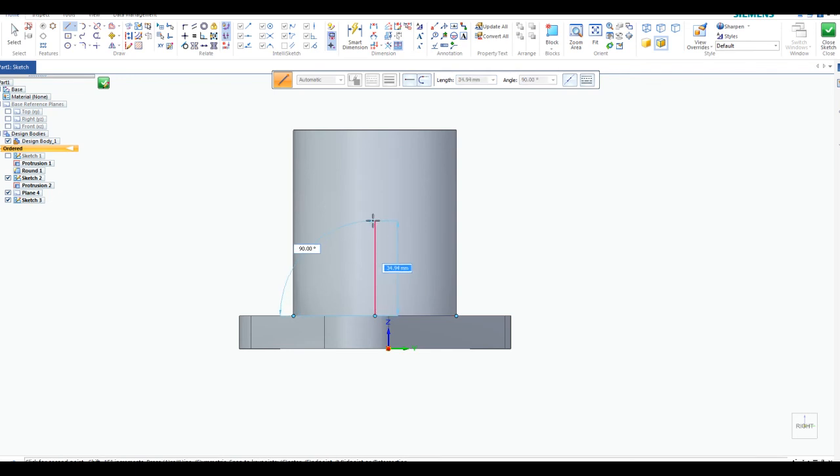Okay, now we have on the drawing 42 from the bottom. But again, we take 42, we subtract 12, which is the thickness. So 42 subtract 12 is going to be 30. So I'm going to type in 30 for this. Pick anywhere in space, hit escape.